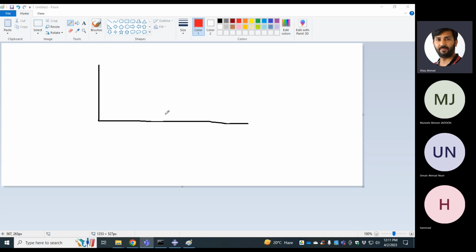However, I have a previous question from the last lecture about the different types of dynamic analysis in Abaqus. So dear students, we have two different types of dynamic analysis. The first one is that we have a structure, like a column or a wall, either an RCC wall or a brick wall, and we are going to apply quasi-static cyclic loading, which is the uniform cyclic loading at each drift level.